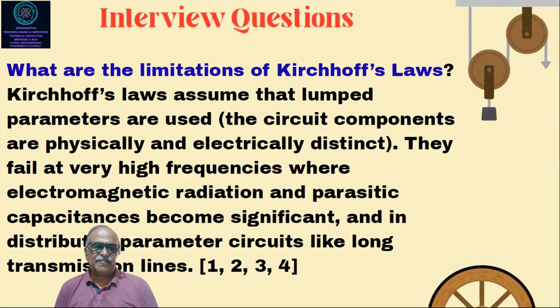They fail at very high frequency, where electromagnetic radiation and parasitic capacitance become significant. They also fail in distributed parameter circuits, like long transmission lines. In a long transmission line there is some opposition, so some losses will be there. That is the point you have to understand and explain: what the limitations of Kirchhoff's law are.